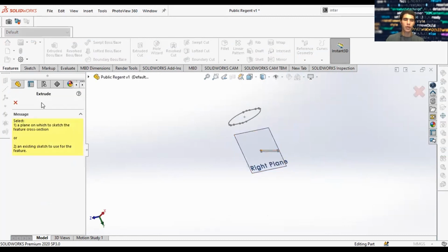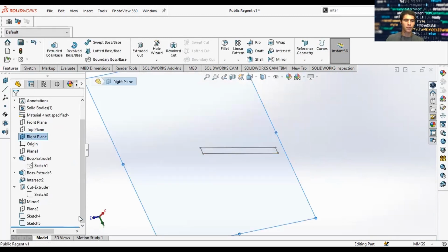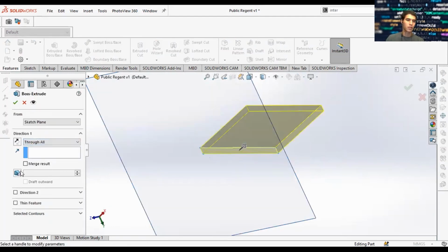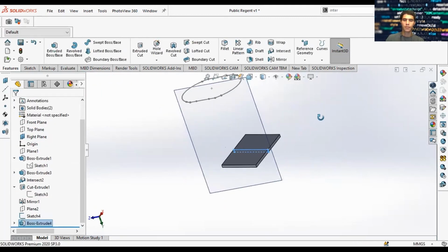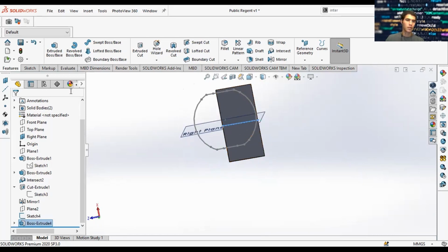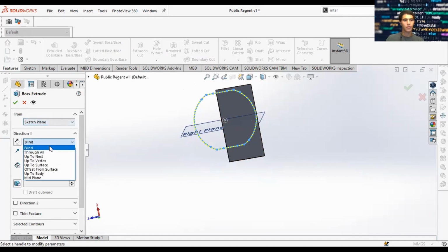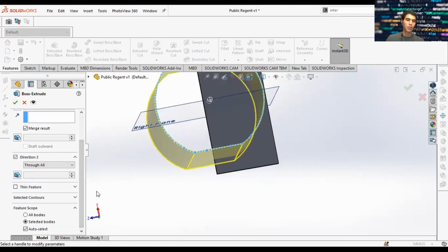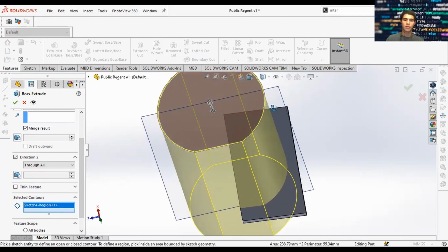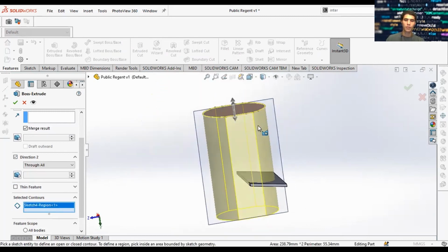Features. Let's go ahead and extrude boss base this leaflet we made. Sketch number 5, extrude boss base, and we'll do it on both sides. And we'll go up here to our sketch number 4, and we'll extrude boss base that sketch through all. We don't particularly want the thin part of it, we just want the inside part of it. So that should give us this result.